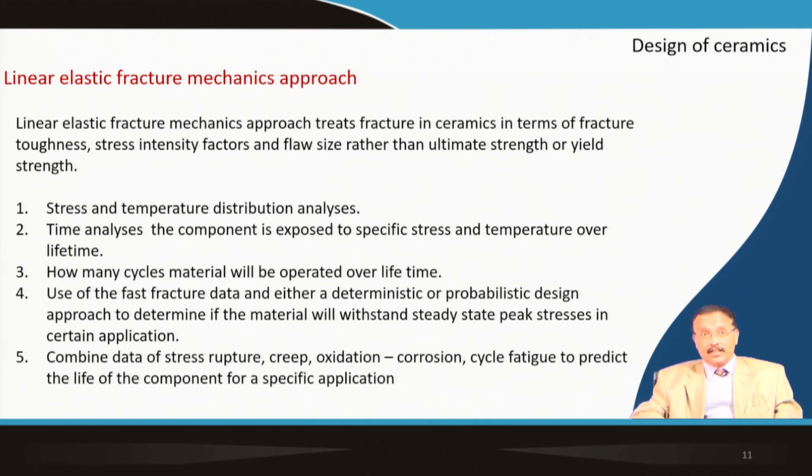Stress and temperature distribution analysis is done, and time analysis of the component exposed to a specific stress and temperature over its lifetime. It is also considered how many cycles the material will be operated over its lifetime.